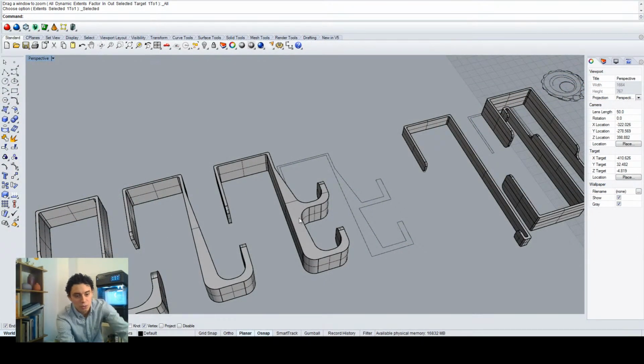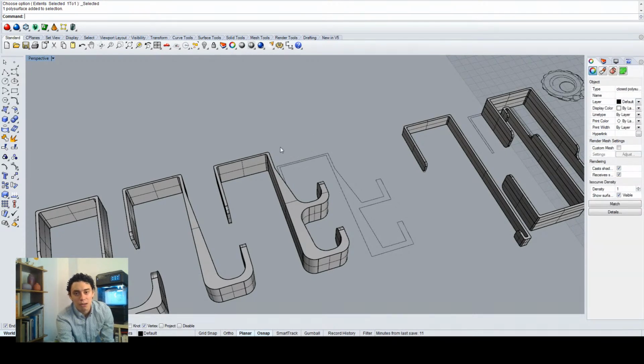So I started with something very simple, very thin, that was basically one of these, disconnected from a different system, right? But you can see the general idea was already here. I was trying to see, okay, how thin does it need to be? These radii become really important because when you get started, it's really easy to forget that anything without a radius is just possible in the 3D world, right? In the CAD environment. If you don't give smaller radii to your parts, it's going to be really hard for you to achieve two things.